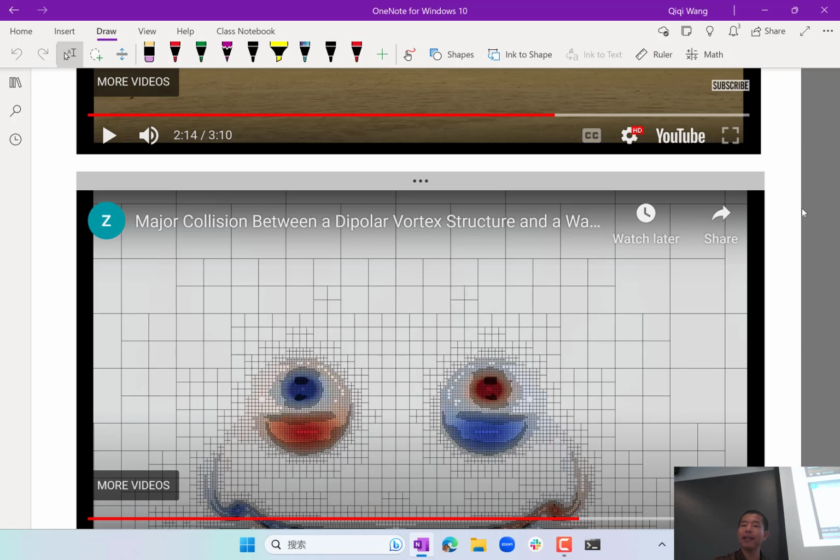What I said before is that if I have pure lifting forces with no drag, not even induced drag, then there is no energy left behind the lifting body. But for an airplane to create lift, especially a high lift, it has to move air downwards. And the energy it leaves behind is not just proportional to the lifting force, but proportional to the lifting force to what power?